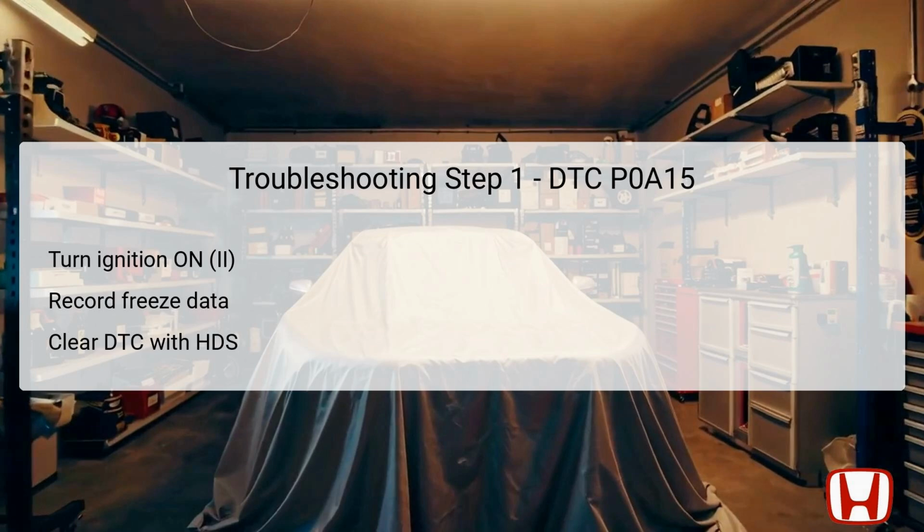It is crucial at this point to record all freeze data and any onboard snapshots, as they provide valuable insights into the vehicle's state at the time of the error. After that, utilize the Honda Diagnostic System, HDS, to clear the DTC from the memory. This will reset the system and allow for fresh diagnostics. Observing the vehicle post-clearing is essential to determine if the same DTC reappears, guiding subsequent steps in troubleshooting effectively.